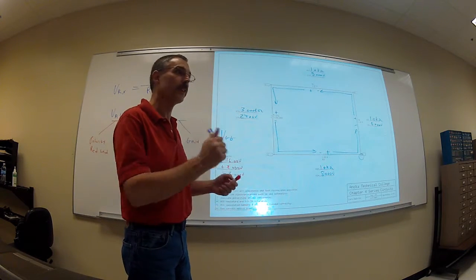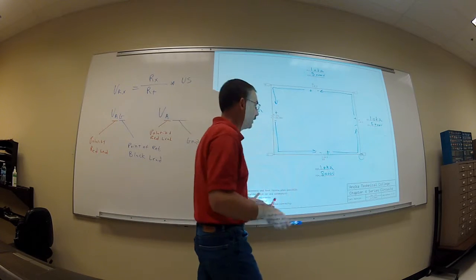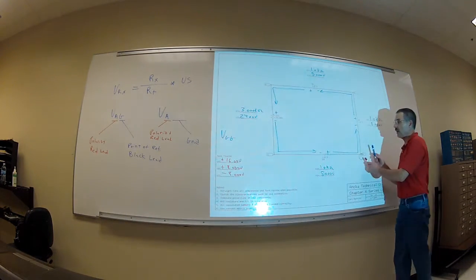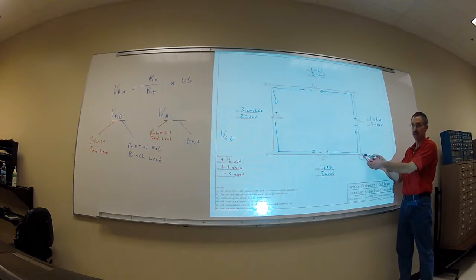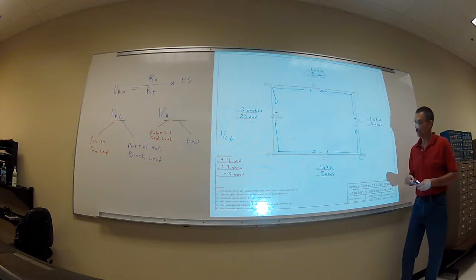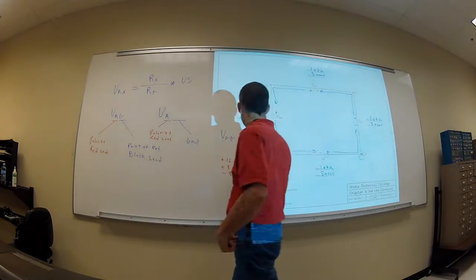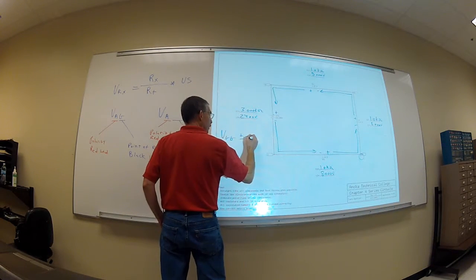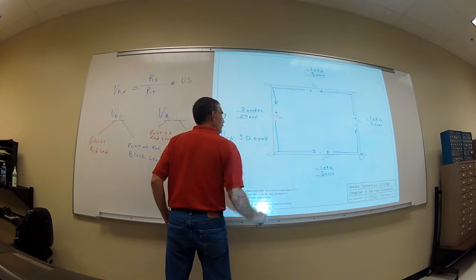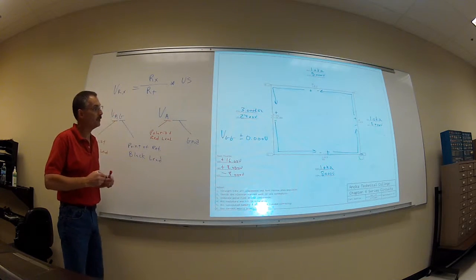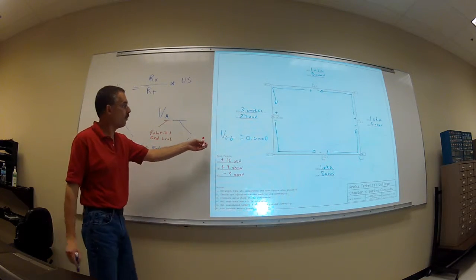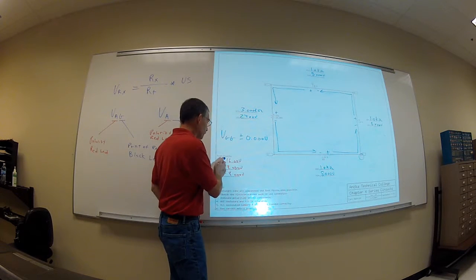Don't forget, even my 0 volts, because the rule is all test points require polarities. So even our 0 volts will get plus or minus 0 volts, so that we always maintain our rule. If we go relaxed on one, then we get relaxed on the positives.